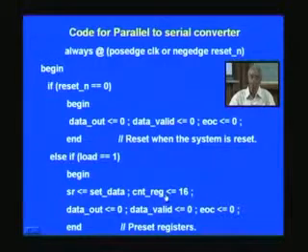And we have a counter to keep track of how many bits we have sent. Since we want 16 bits to be sent in total, we will just initiate this one counter. This is 5 bits as such. So 16 is loaded onto that here. It's a preset value. And once again, you deassert all the outputs here.